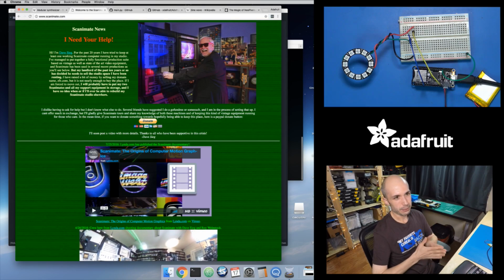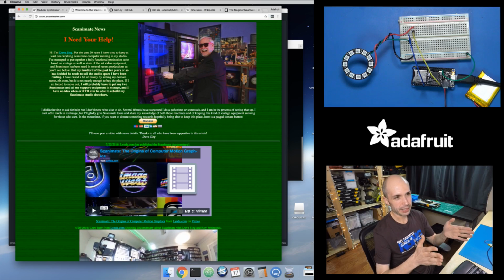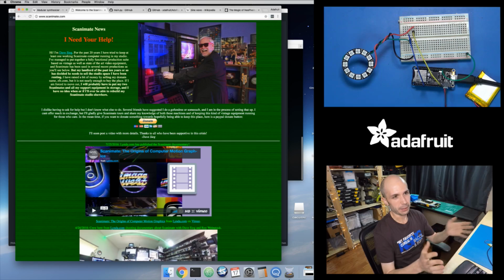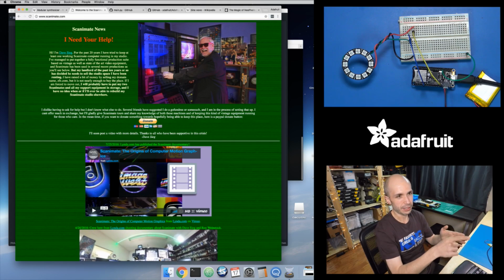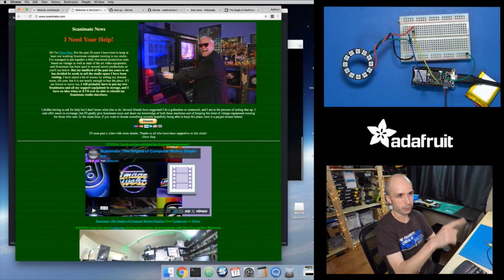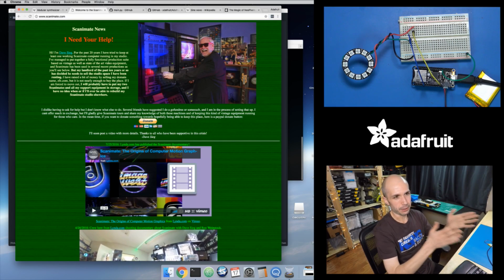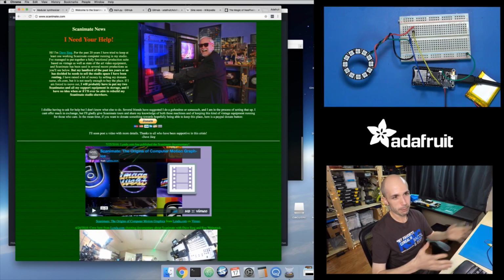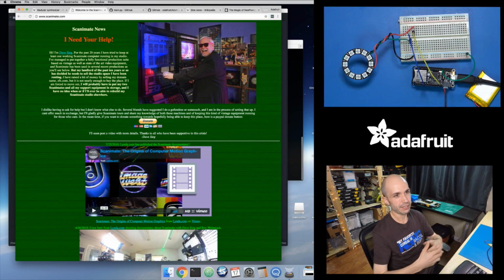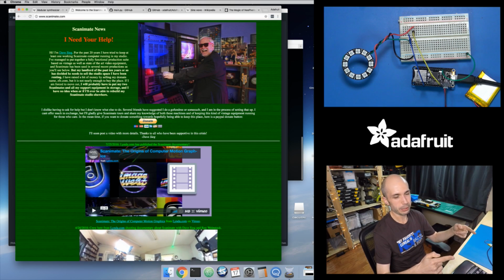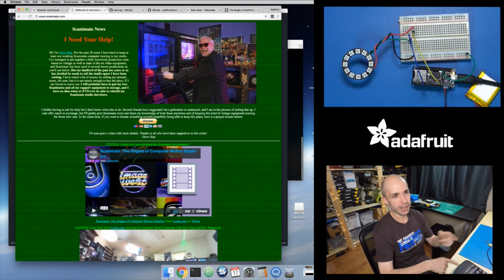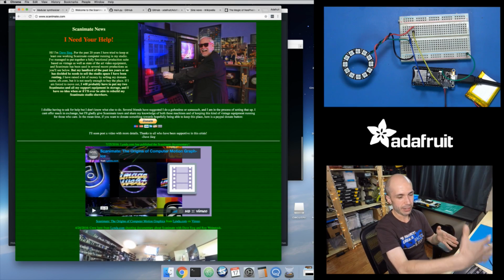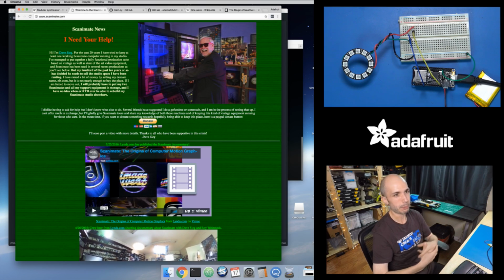A TV is really just, there's some magnets that drive an electron beam, and it scans across the screen very quickly, and the magnets are modulated in a certain way so that there's a vertical retrace and a horizontal retrace. And depending on how long it spends at a certain point in time, that's just more intense of a signal that you get there. So if you modulate those magnets, you can just think of this as a signal processing problem. Just what signal do you feed into those magnets to control how that electron beam scans across the television tube? And then that will just change how the tube lights up and what you display there.